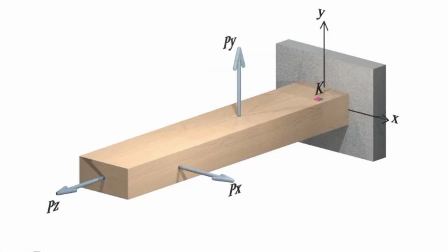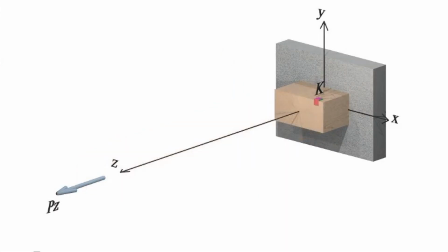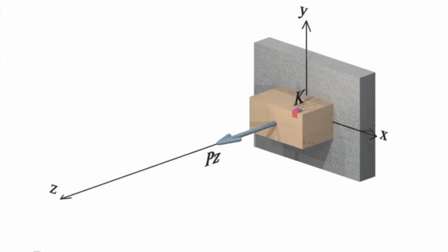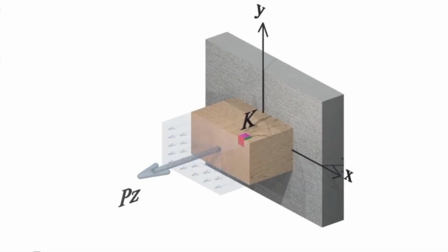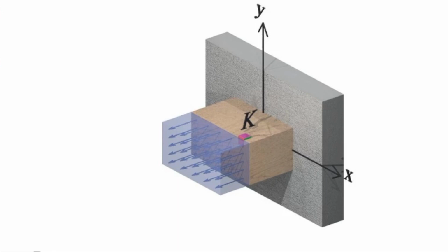Okay? All right, the last one is force Pz, which is going to move along its own direction. This force is not producing any moment because this is just moving along its own direction. Once this force gets there, it is going to be an axial force, tensile, and stress is going to be uniformly distributed on a section. So I would determine three normal stresses produced by axial force, moment about the x, moment about y, and I would determine shear stresses produced by Vx and Vy, and then make up the stress element in a three-dimensional way, and then calculate stresses at that point.